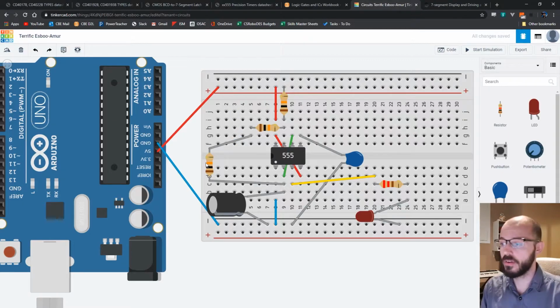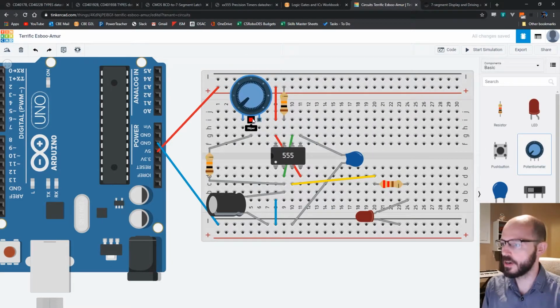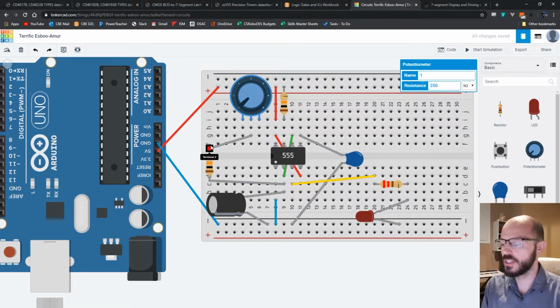Another thing you could do to play around with the resistance is instead of using just static resistors, you could use a variable resistor, like a potentiometer. So if I hook up a potentiometer here, let's still use this initial 10,000 ohm resistor so we just get more resistance. The ones that you have in your kit are also 10,000 ohm potentiometers. I'll hook up my resistor to the middle pin of the potentiometer, and then one of the outside pins, I'll just jump over to where this resistor was initially going.